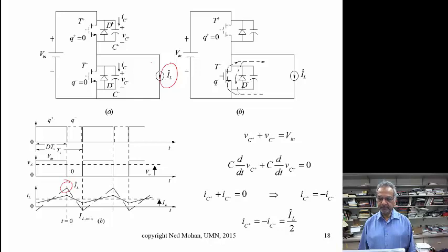And so we are really looking at this transition during this delay time where the upper transistor is turned off and the lower transistor is turned on here. Okay, so that delay time that I talked about. So what happens is that during this delay time, both the signals are 0 to the upper transistor and to the lower transistor.